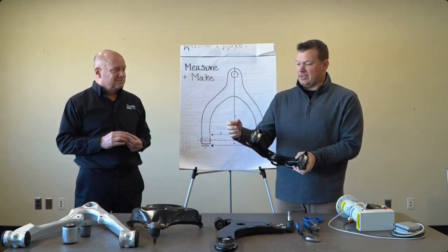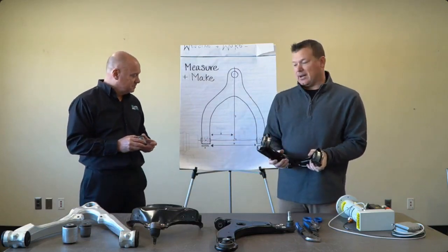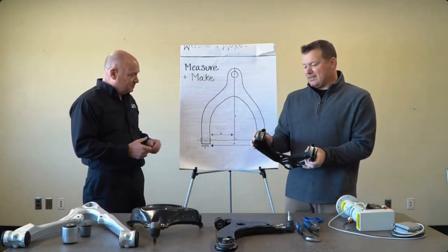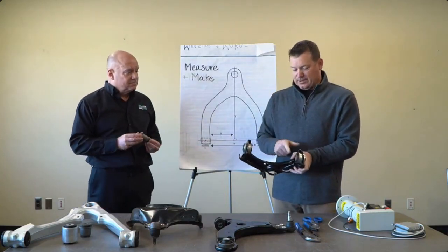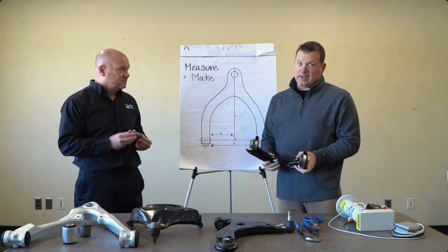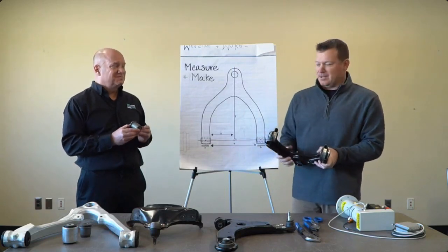So just pressing to a position like I talked about earlier is not going to work. You're not going to get acceptable results. When they go to put this in the car, it's not going to fit. And surprisingly enough, in these applications they hold these tolerances that Glenn just mentioned to a pretty tight tolerance, like less than half of a millimeter in some cases.